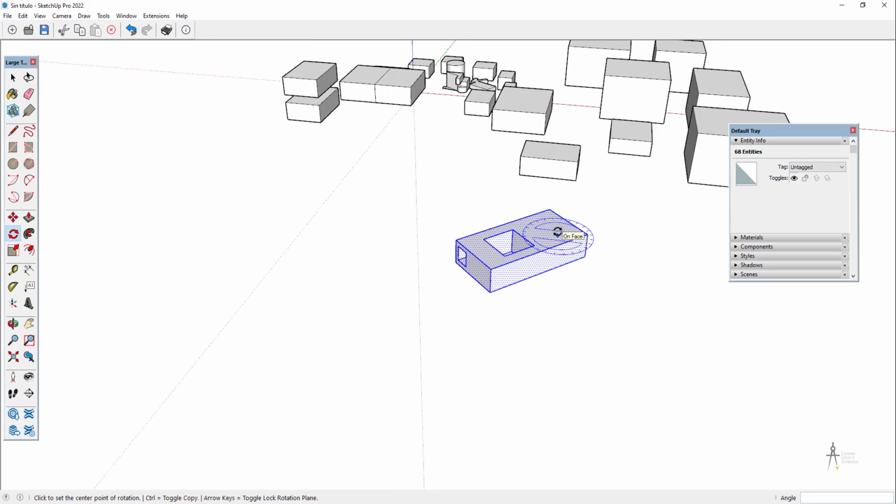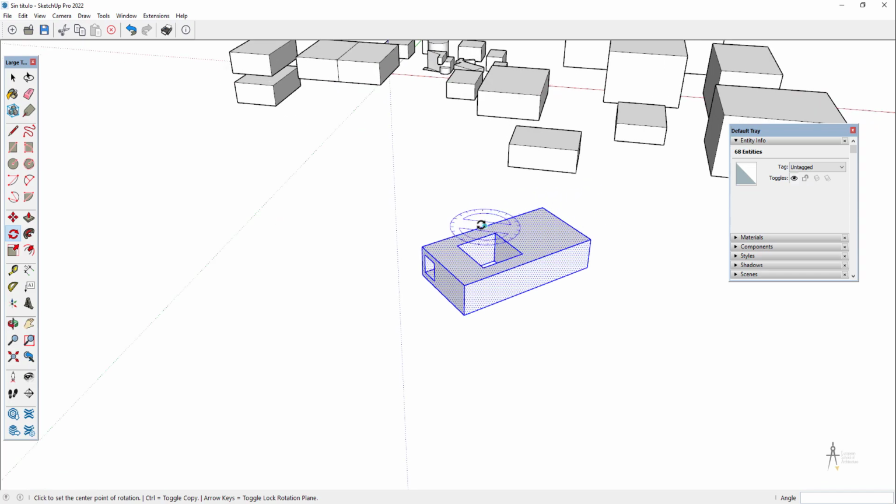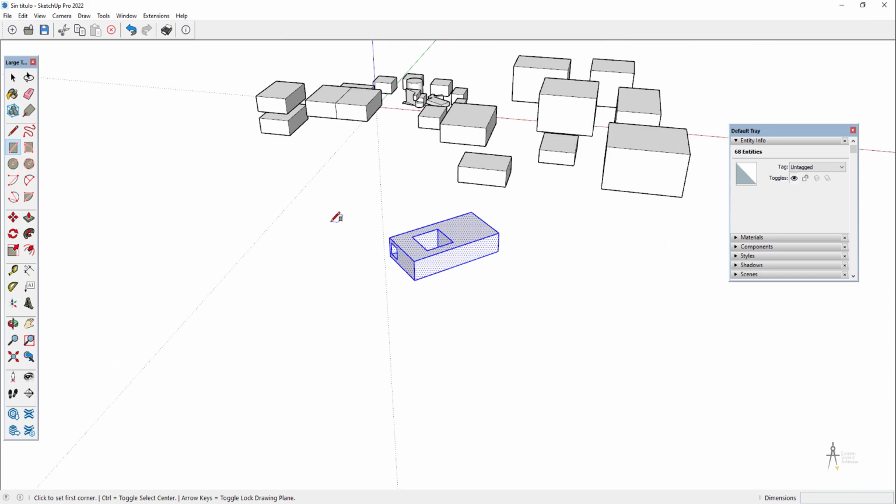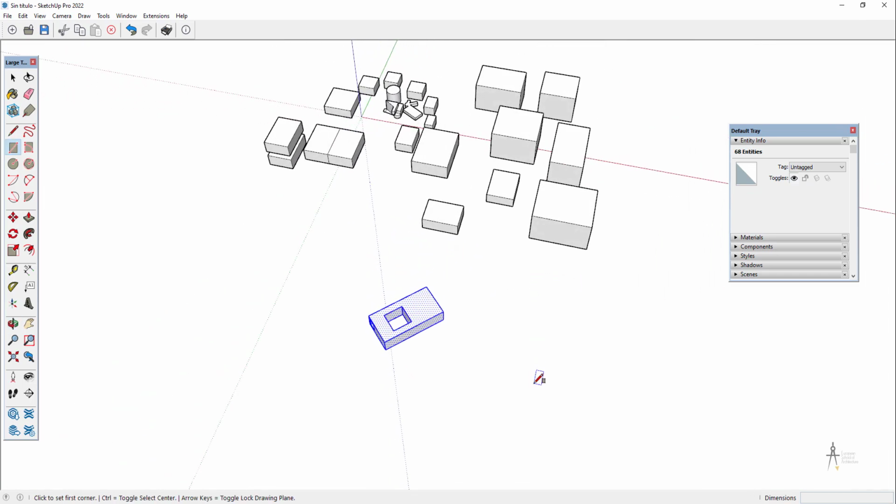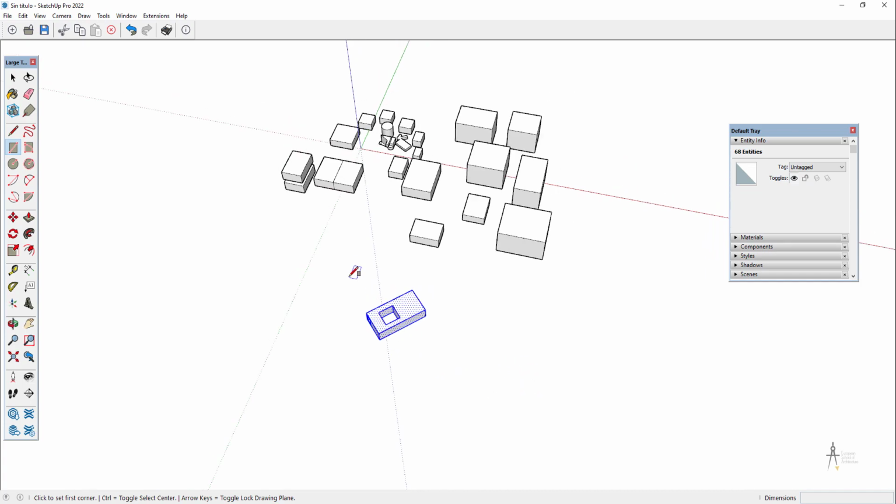Okay, we're gonna carry on checking out tools, and we're gonna see this one, which is Follow Me. Follow Me is below push pull, and it basically does the same thing push pull does, but in a given direction. Okay, and for this I would like you to try to find an angle that is like an elevation. So you see how this works.